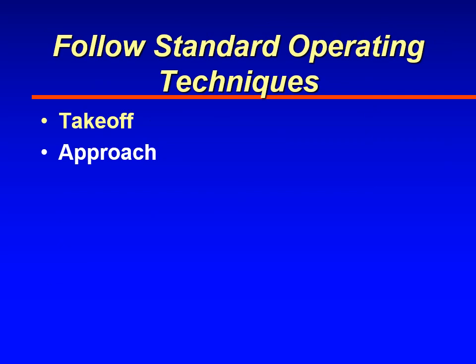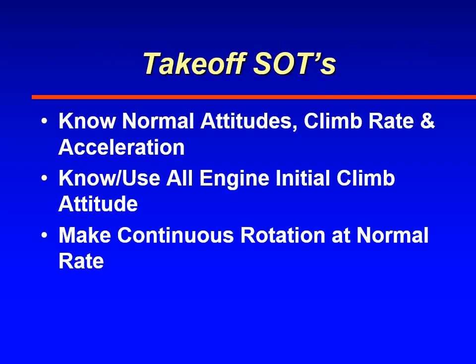And standard operating techniques can be broken down into takeoff and approach. This is very similar to what we call control performance for instrument flying. If you know the numbers, if you know the pitch attitude, number of degrees up or down, the climb rate, the power setting, and the airspeed, then you will know your standard conditions for the aircraft.